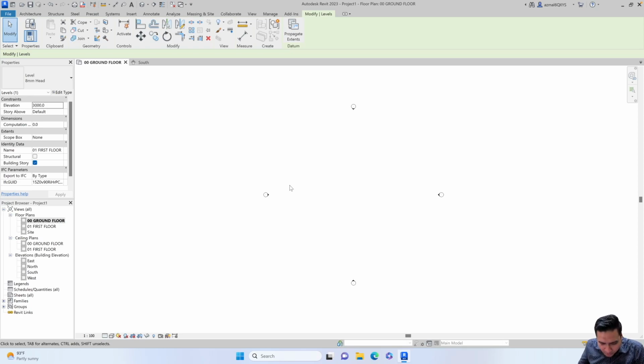Before we go further, how do you navigate in Revit? By using the mouse, for example, scrolling your mouse helps you zoom in and zoom out. It's similar, I believe, to any other 3D software, for example SketchUp, and even Autodesk AutoCAD. So you use the scroll wheel of your mouse to zoom in and out of your drawing. Okay, now how do we do the grid?